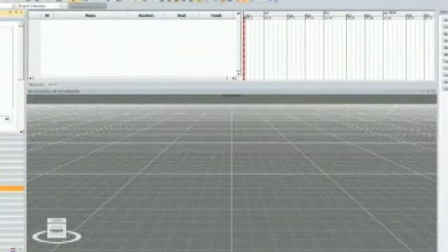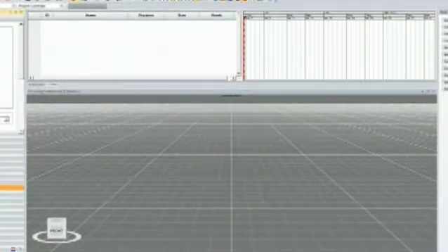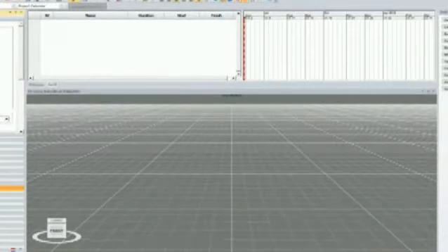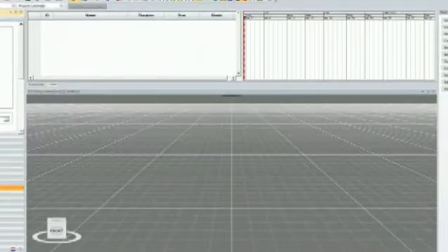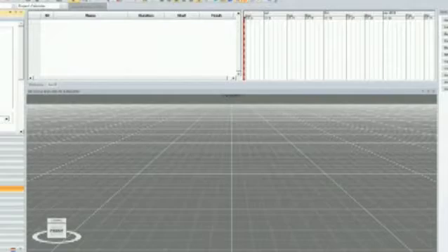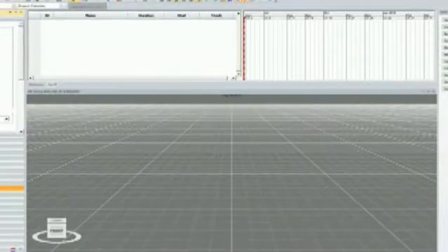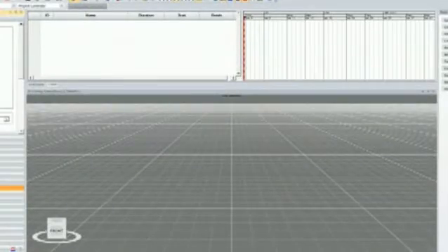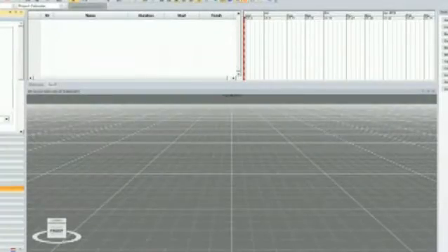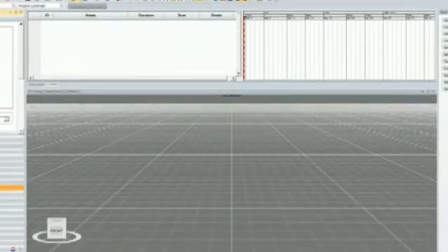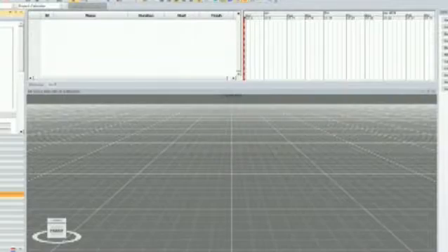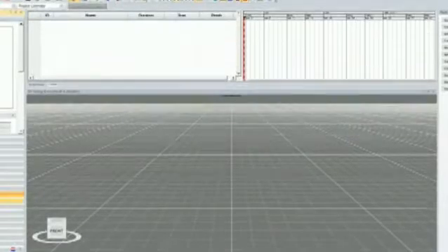information, baselines. We can create multiple baselines. We can save as many baselines as you want in Synchro, and we can do side-by-side analysis and comparison of those baselines. So I can have 2 3D windows in Synchro running multiple baselines, following different schedules, right? So baseline A, January 1, baseline B is February or March 1. And I can view the differences of those baselines directly in Synchro. We can create movies and or animations in Synchro, which can export out to AVI files for presentations.